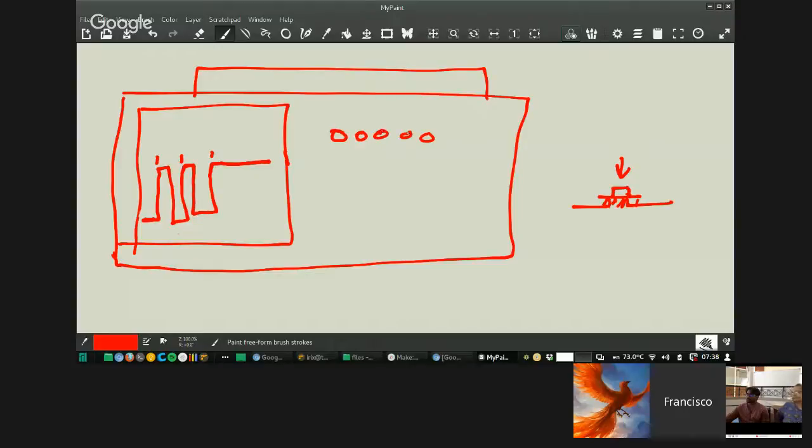In my opinion, because this is digital fabrication, it is better to do hardware debouncing. But in the industry, because they are making millions and millions of copies and they want to save every component, they do software debouncing. You can do software debouncing, but for newbies, what I recommend is just doing hardware debouncing.